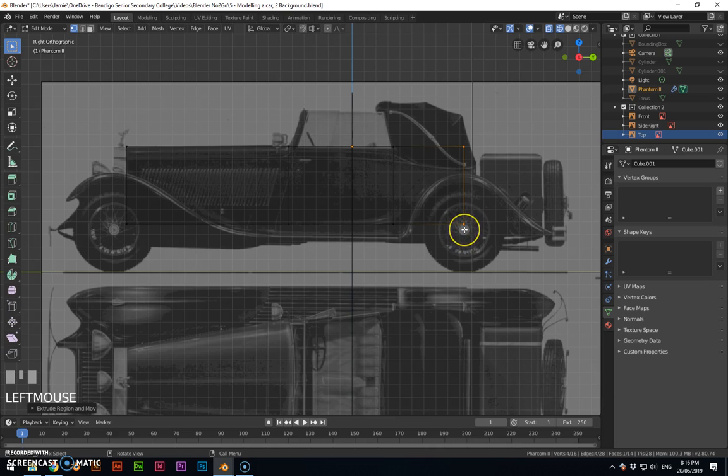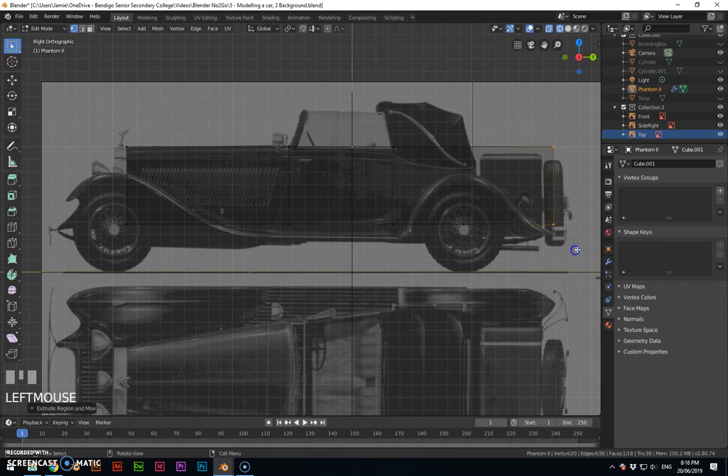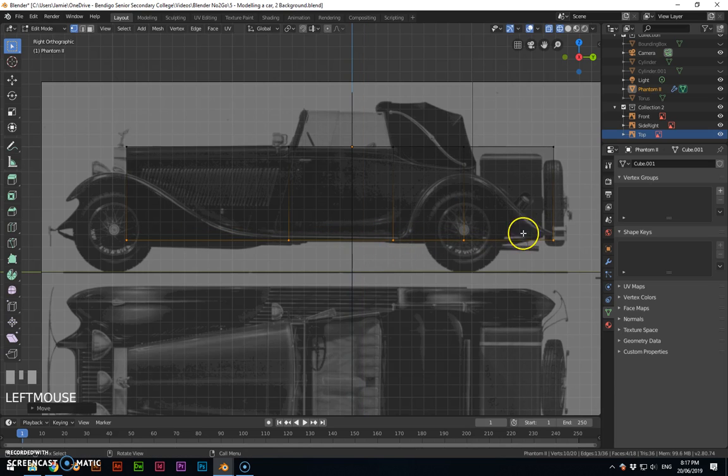So you can see I'm using that little point there as a reference mark, and then extrude right to the end. So here I need to drop the bottom line of the car, grab Z direction, and just drop it down so it touches the bottom. And then obviously, because that rises up, I'm going to need to change that line and adjust the tops down.